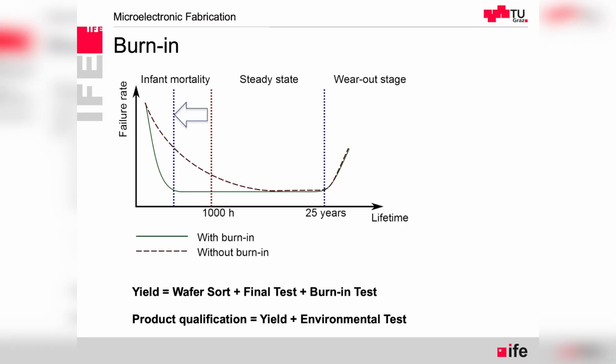Then regarding the fabrication issues, once we have got as far as the packaging, we're almost at the end of the cycle of the production. But what has to be done is the so-called burn-in. It could be that some parts are weak. They have some weakness, and we plug it in the application and it works.